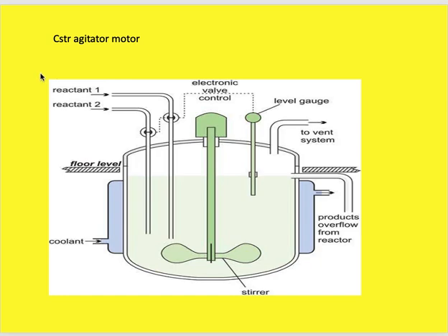So the agitator, and we mentioned that we need to keep two sources of electricity available at all times for the motor, source A, source B. If you lose source A, you can use cut in and introduce source B, so as not to stop the agitation, and maybe this leads to runaway, and a runaway reaction is not recommended at all for this type of reactor, because it may harm the equipment and make them